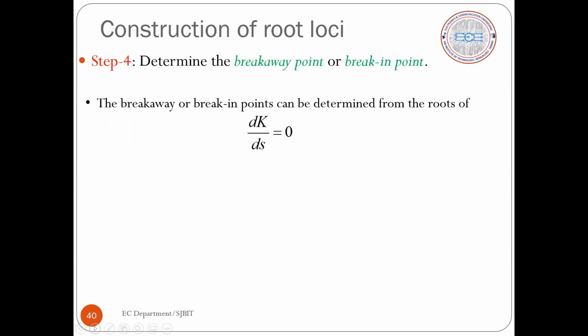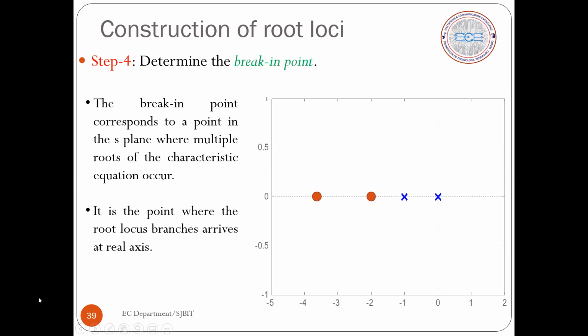Similarly, what is a break-in point? The break-in point corresponds to a point in the S-plane where multiple roots of the characteristic equation occur. It is a point where the root locus branches arrive at the real axis. We say that the root locus arrives, whereas at breakaway points, the root locus departs.